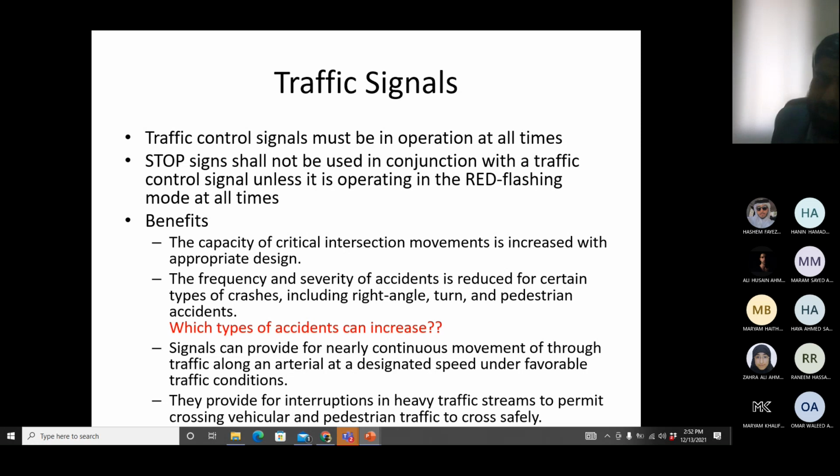And it has happened many times with me. It must have happened with you as well. And if you want, you can observe it. Okay. Whenever you are at a roundabout in the peak hour, just observe. The main street will always be operating primarily because it will not give the gap to the other street. Okay. So a signal will make sure that even the secondary or the minor street also gets enough chance.